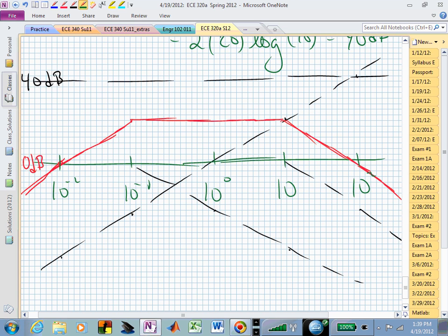So now we are designing, so you can sketch on your napkin some Bode plot, and you can create the transfer function. You can do system identification. You can identify the system that corresponds to that Bode plot. Once you have your transfer function, you should be able to, maybe with a little more study of chapter 14 and 15, realize that transfer function. So now you're doing system realization.